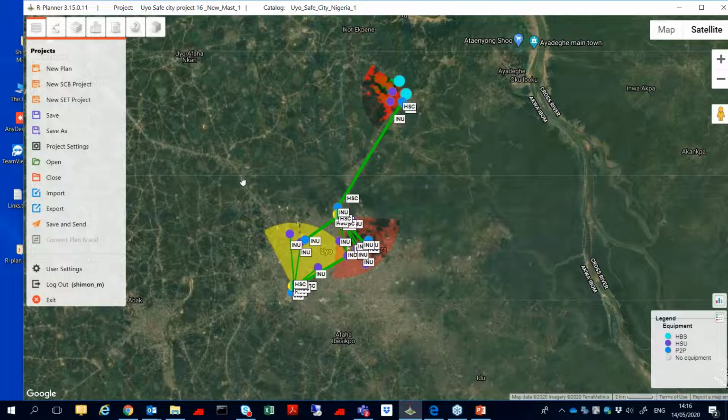Remember, synchronization is mostly required to avoid collocated interference. Now, if there is another third party on the same tower or transmitting nearby, we cannot synchronize RADWIN equipment with Ubiquiti equipment, or with Cambium equipment, or with other vendors. We can take care of our synchronization to avoid self-interference.